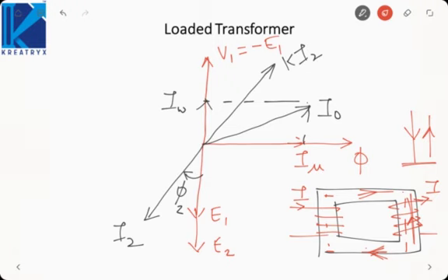So actually the opposition in the MMF or the flux comes from the winding orientation. It has nothing to do with the phase of the current. But in phasor diagram, we cannot show the winding orientation. So what we do is, we draw both the phasors in opposite direction to satisfy the Lenz's law, or to show that both MMF try to cancel each other. So whenever you are doing the numericals, you will take I1 dash and I2 in same phase. Okay, because the opposition comes from the winding orientation and not the phase of both the vectors. So remember this.